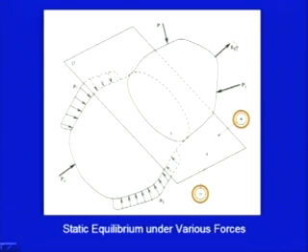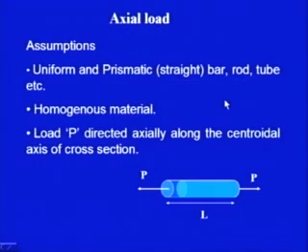If you want to see the internal body forces, then we need to cut through a plane. Let us say I have a plane Q and I want to cut the object through this plane. I can easily visualize that under these forces the object is under static equilibrium. So how are these internal body forces set up to resist all these forces? We can visualize these body forces just as we do the surface tractions.